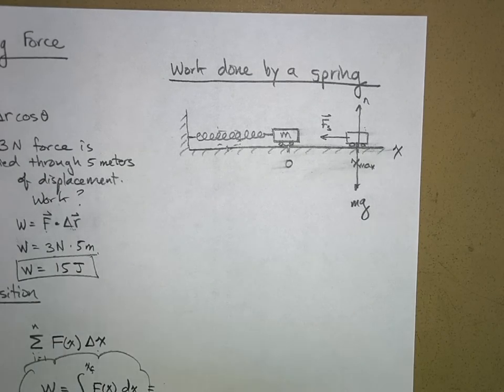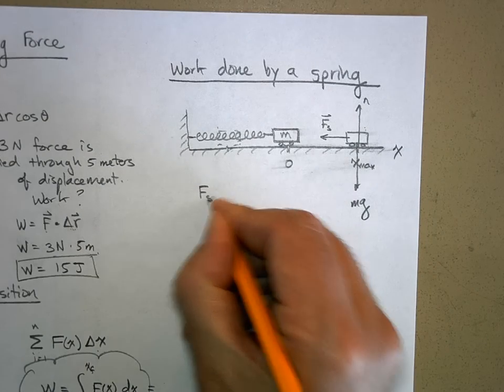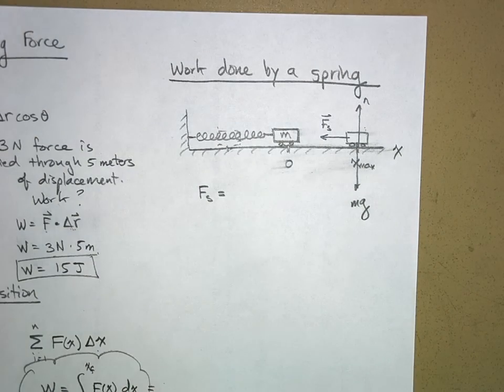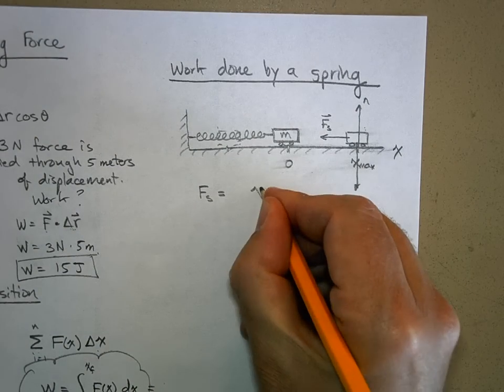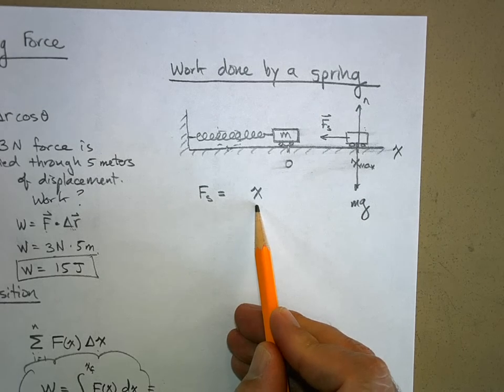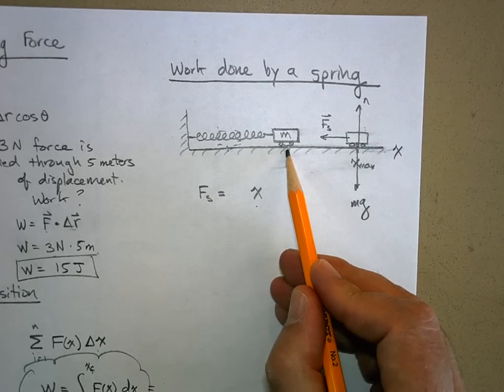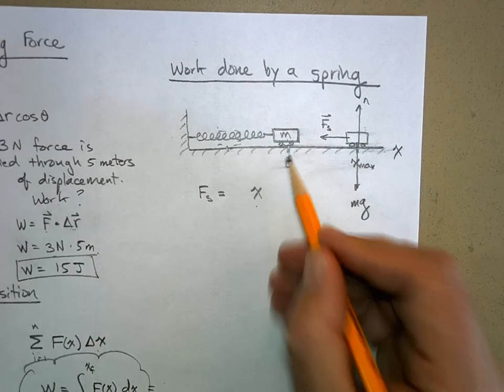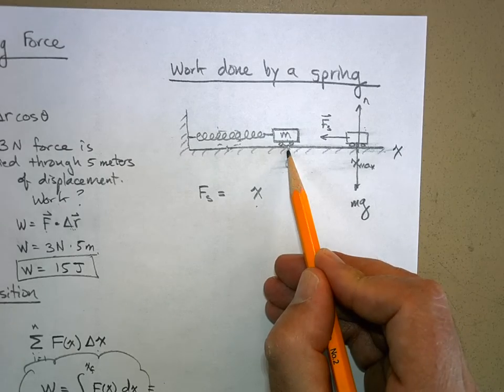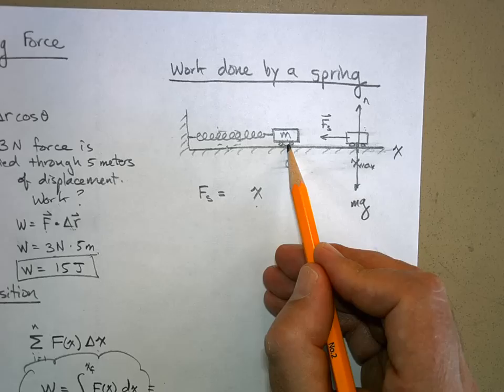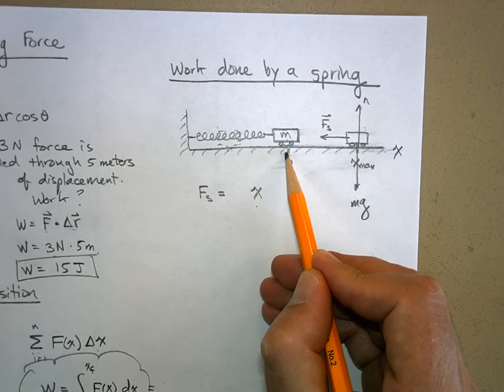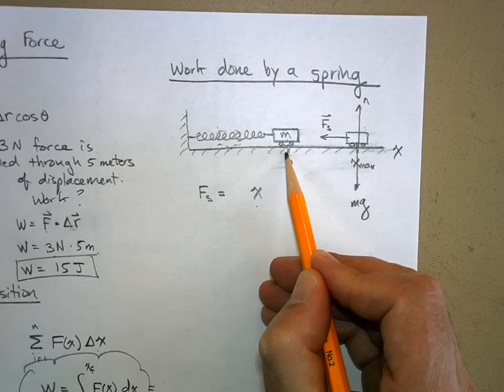assume that these are Hooke's springs, or springs that obey Hooke's law, which says that the force of the spring is directly proportional to my position, or my position away from the equilibrium position. This is called the equilibrium position because at this spot, the spring applies no force at all to the crate. I'm defining the origin to be where the spring is in equilibrium position. Yes? Okay?